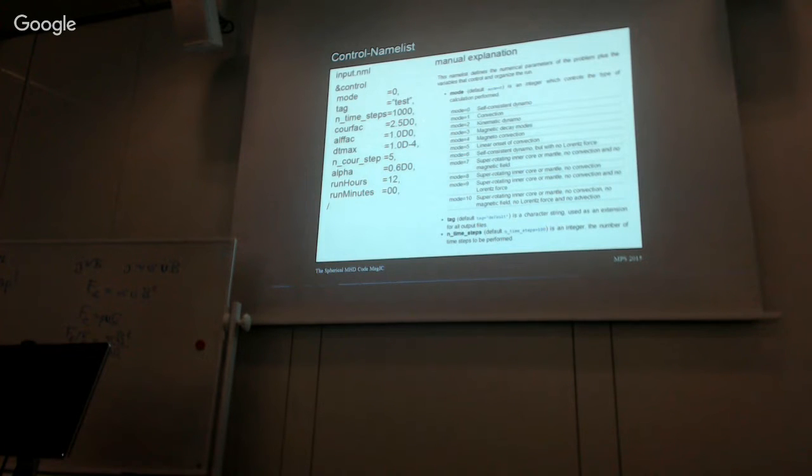Matti, do you know what the Courant-Friedrichs-Lewy criterion means? No. So let's say you have a numerical grid, right? And say you have two grid points. Now you look at your flow velocity, and you look at the time scale you need to advect any quantities from one grid point to the next.